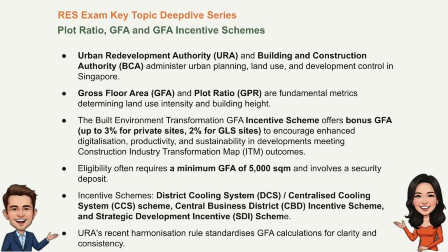What about productivity? Productivity focuses on using advanced construction methods to build faster and more efficiently. This involves significant use of prefabrication technologies, things like PPVC, prefabricated prefinished volumetric construction. Like building with Lego blocks, almost. Sort of. Manufacturing modules off-site and assembling them. Also, prefab MEP systems, pre-assembled mechanical, electrical, and plumbing components. For offices, structural steel use is encouraged. The goal is a substantial productivity improvement, often over 30% compared to older methods. And for residential projects, they also need to achieve a good quality mark, QM score, ensuring speed doesn't sacrifice quality. Right, build faster, smarter, but still build well.